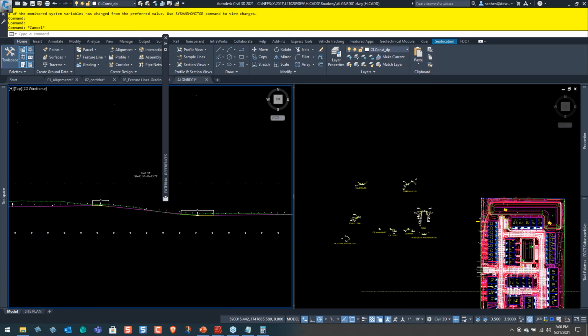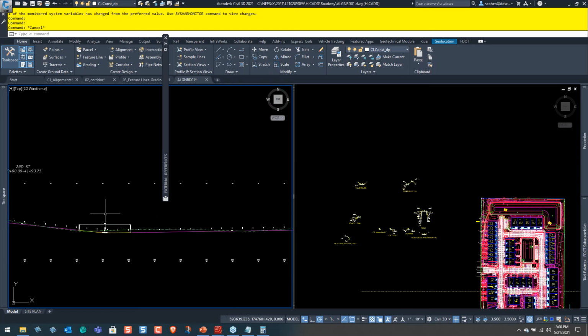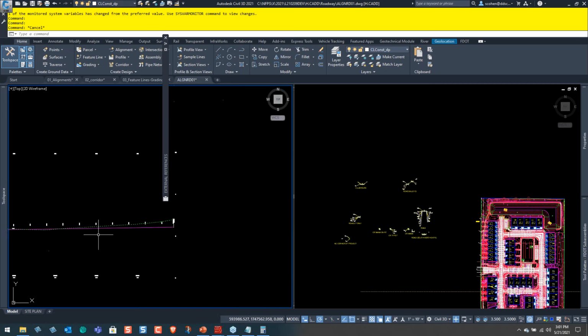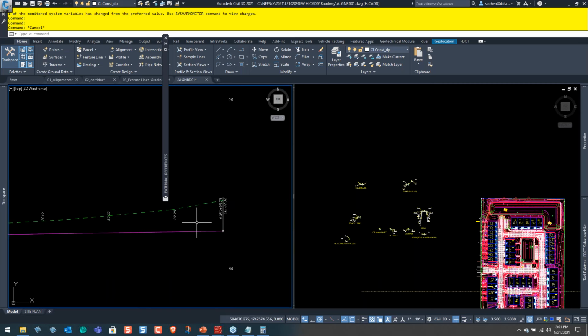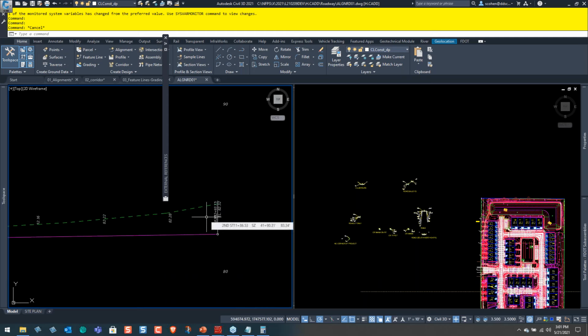You can see here, let's see, 2nd Street. Yep. Notice how this thing here was sitting above. I had my site completely balanced. I had 100 cubic yards of cut. It was awesome. I had the site balanced perfectly. We were going to do retaining walls. He said, no, I don't want to pay for an extra $100,000 worth of retaining walls. And we were like, okay, I had to change my entire design to go below here to match into existing so I could get a ditch to pop it up. As you can see, I'm at least 2 feet below here. I gotta be. I'm at 82 and this is at like 84. So there's my 2-foot ditch, right? I have to be there.